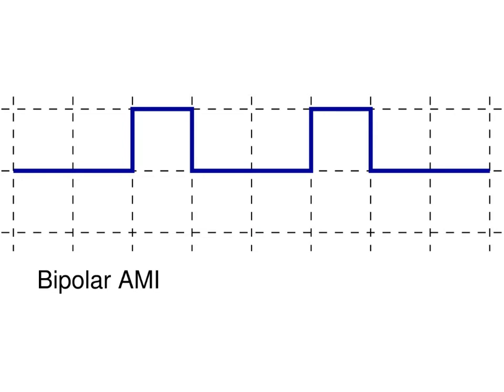But with bipolar AMI, by definition, it should be positive or 0, and if we had a positive, the next non-zero value should be negative. But for some reason, if this is the received signal, we received a positive, it tells the receiver there's an error. Something's gone wrong in the transmission or in the communication system.